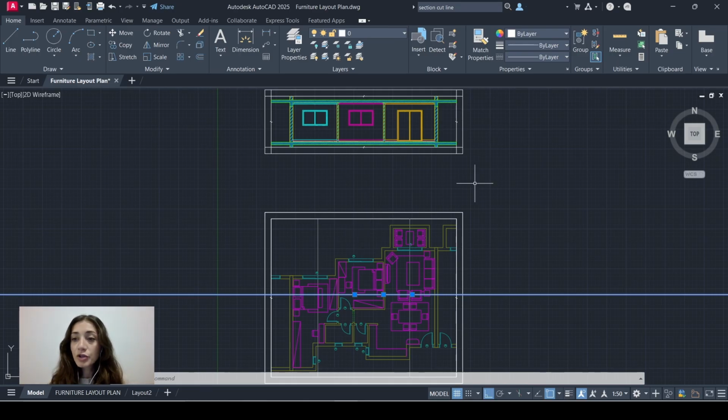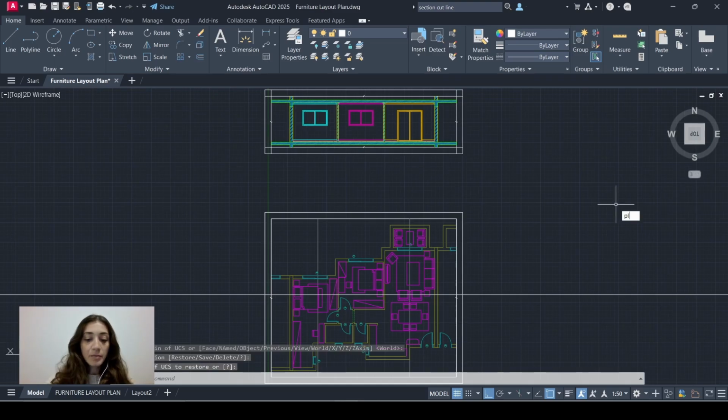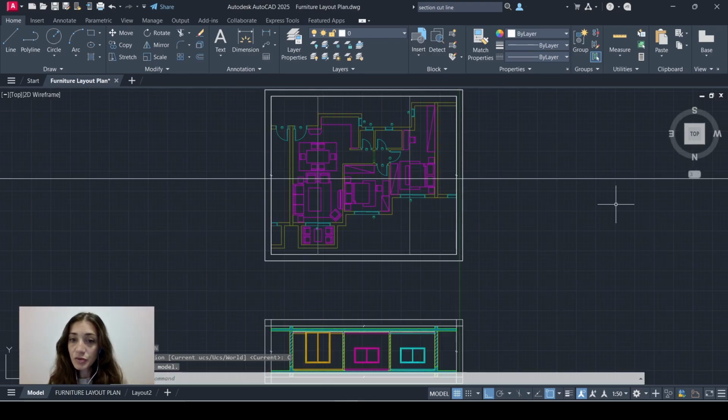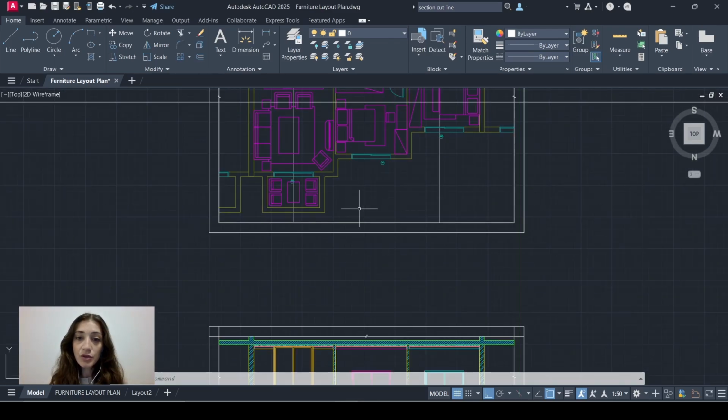So before I start drawing, I'll just adjust the orientation, and please refer to my user coordinate system video to see how I created these custom orientations. But for now, I'll just select UCS3, type in plan, and then select current UCS. And this way, it should be easier for me to project what I see if I'm standing here and looking at the apartment from the outside.